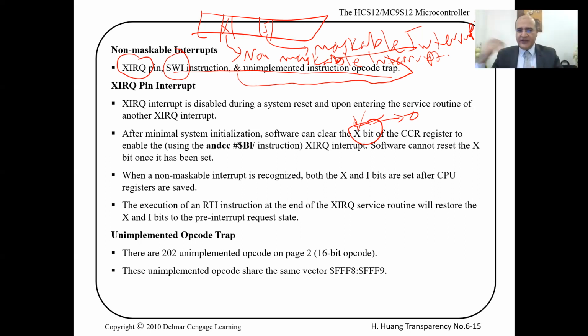We said at the beginning in chapter 1 or 2, I forgot, that all machine instructions for HCS12 are either 1 byte or 2 bytes, right? The 2-byte ones start with an 18 hex. And we had a list, and the instructions for the HCS12 are defined. They're a limited number. If you put any number in program memory, and the program counter fetches that thing from program memory and doesn't find it among the recognized instructions, it will cause a trap.